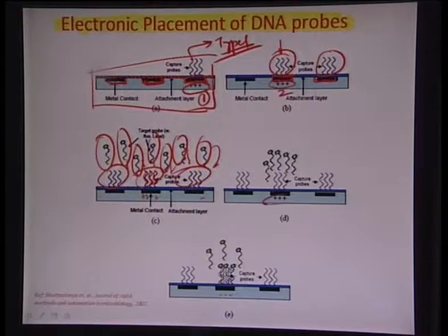Effectively, and this is shown here, you have electrophoretic mobility driving this negatively charged DNA onto the DNA immobilized on the middle electrode. And mind you, these are all fluorophore labeled, and we are going to test whether it is complementary to a particular type of capture probe or not. If it is positive in that sense, there would be a binding action. And so when you wash this chip after the electrophoresis process is over, it does not get rid of these fluorophore labels. Therefore there is a pixel which is turned on, from which one can gauge the sequence of the target that you are looking at.